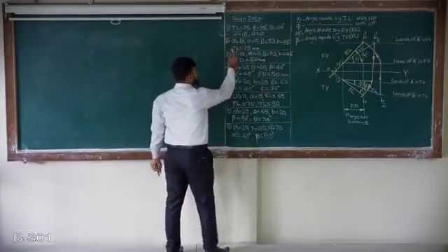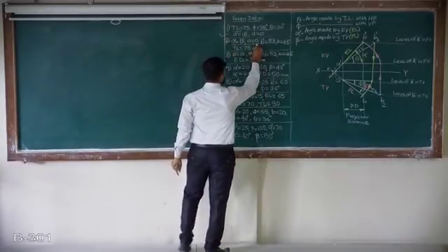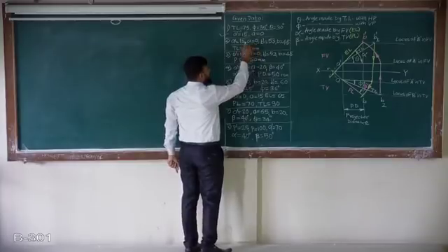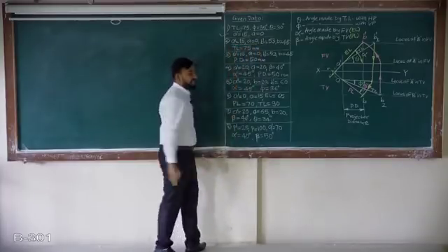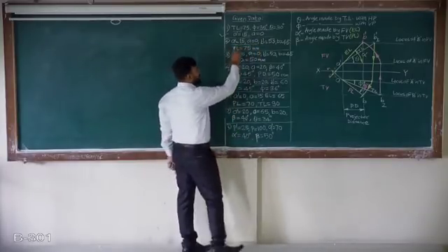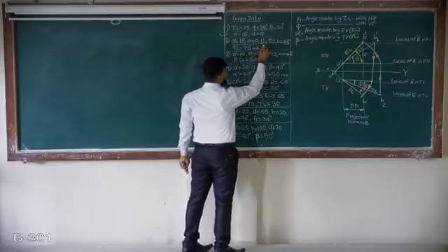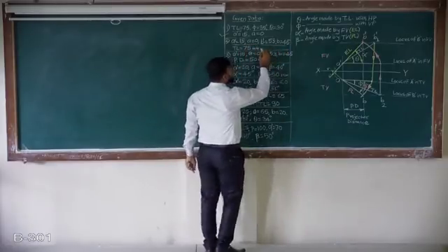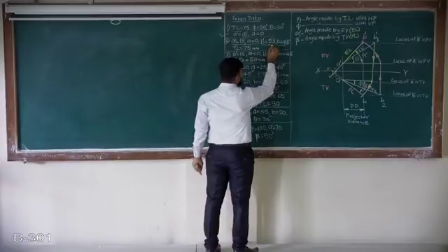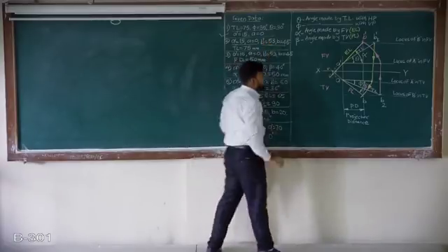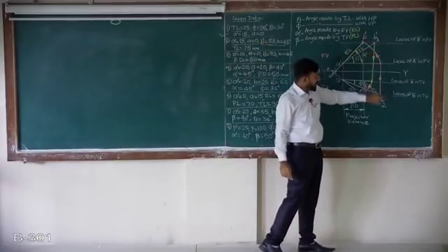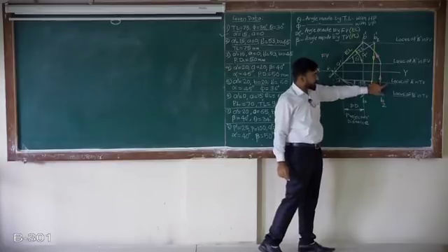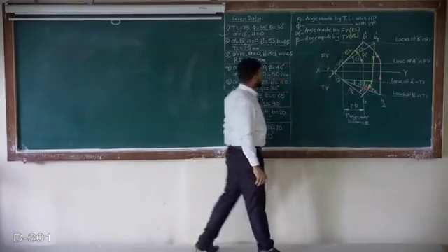So it is very simple. Point A is in VP, whereas point A dash is 15 mm above HP. Same, point B dash is 53 mm above HP. So I am saying that we have the locus of B dash, locus of B, locus of A dash and locus of A, the corresponding front and top views.